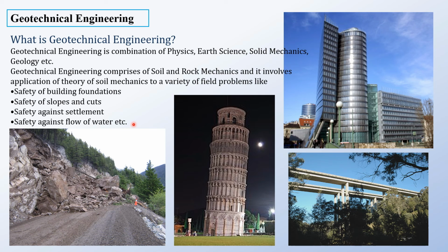So this is the aspect, like how much is the permeability or the rate of flow. One more case is suppose if you want to build a building below the ground level, and you will be obviously excavating. When you excavate, if the water level is quite above, then again you have to apply some remedies like pumping out, etc. What rate of pumping is essential? All these calculations depend upon what is the rate of flow inside that pit that you have made.